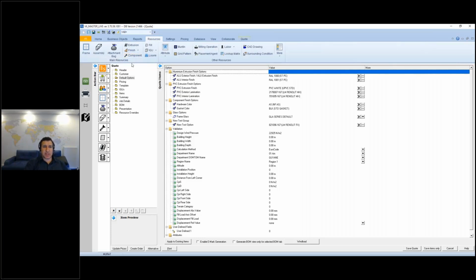And especially for customers using the native functionality for handling component hardware finishes, sometimes it makes things difficult. Let's say you have a powder coating finish that you want to add in the components, and you have 200 powder coating RAL colors in your finish group. Before, you had to add them all one by one, and it was quite a big process. So right now it's not that anymore.